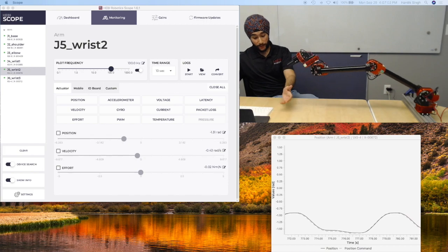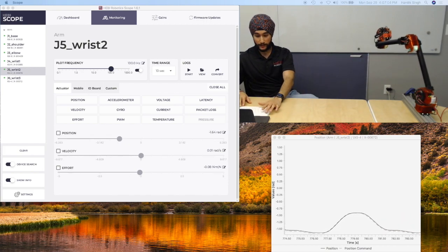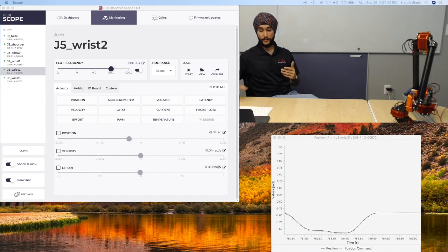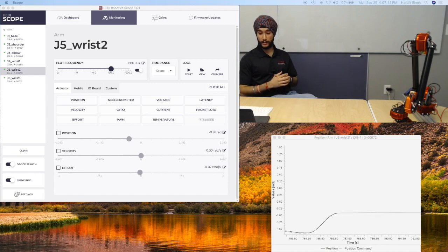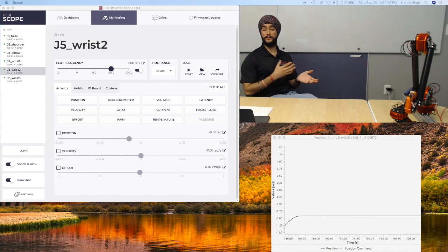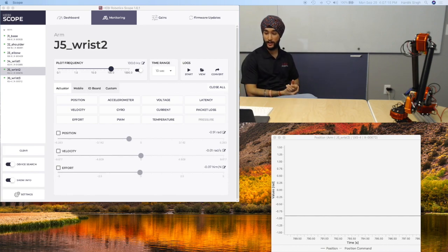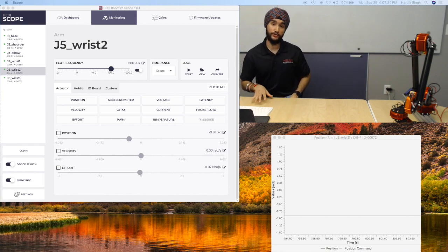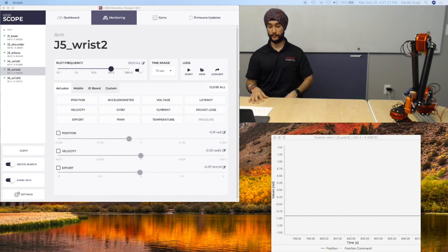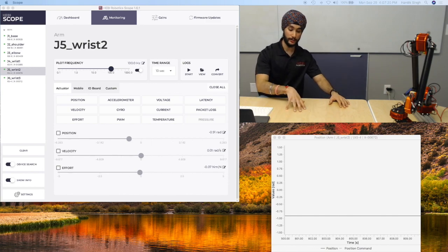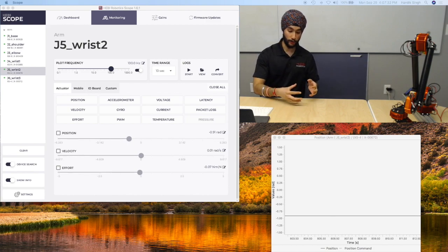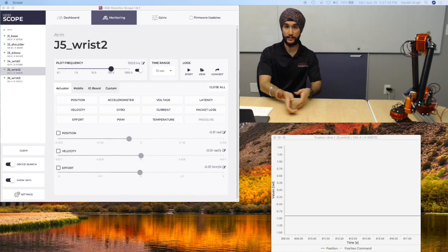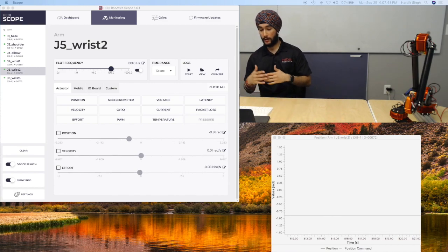As a final note, what I will emphasize here is that what we are doing is not restricted to just robotic arms. The concept of trajectory generation and trajectory planning has to do with simply how to get from one point to the next with a given hardware, with given actuators, with given motors and embedded systems like this. Whatever configuration you use, these principles still remain just as useful. So whether you're doing this for a mobile base that's moving around, you're going to be wanting to create trajectories for those individual wheels so as to prevent your mobile base from just suddenly moving around, but instead creating a smooth velocity, acceleration, and position profile.